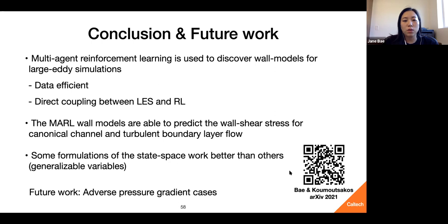That's usually what the LES does, so even in the cases that I'm mentioning, those are the boundary conditions that we use. But in order to obtain that wall shear stress, we solve a secondary problem, this type of ODE or the log law slope. So there are two different problems.